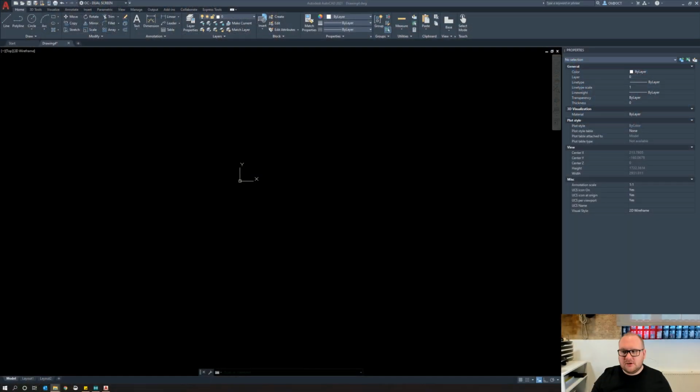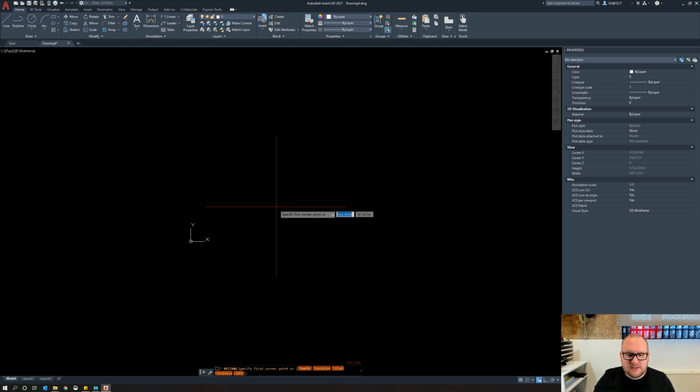So something that people don't often talk about in AutoCAD is their libraries and why we have them to make our life easy. So things like truss, steel deck. And what I just want to quickly show you is a little workflow that I personally use to create my block library and make sure that I've kept parts that I think are relevant. So I'm just going to jump back into the screen and quickly create a block. I'm not going to go into too much detail of what it is. I just want to go through the process.